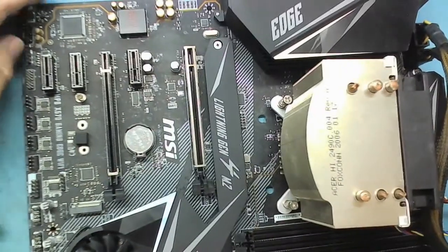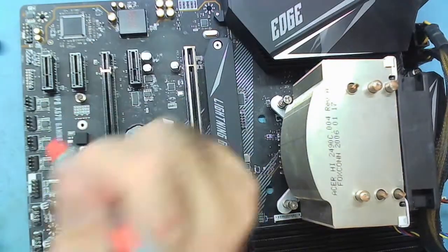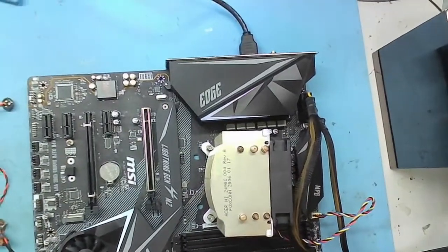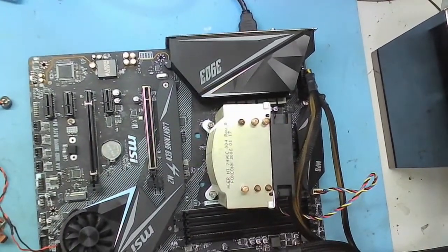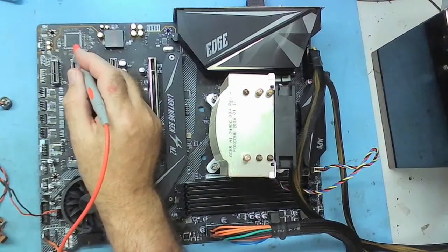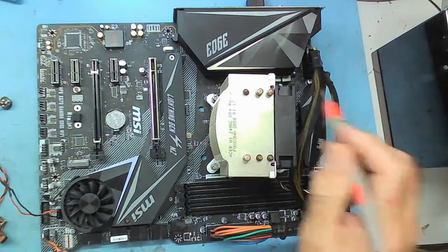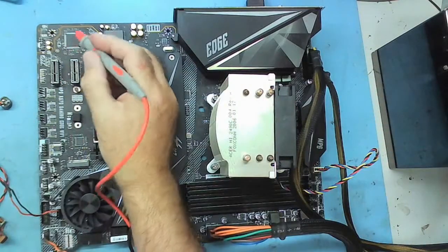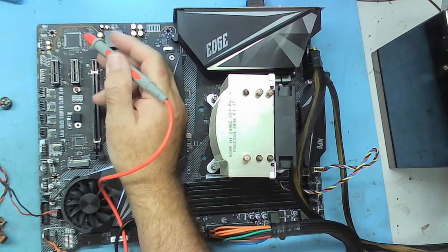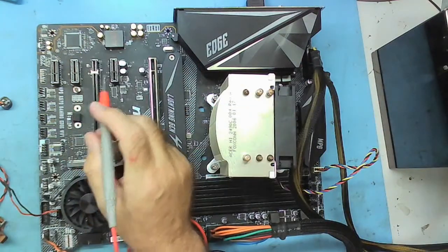Well, this is going to vary a bit from one chipset to another. But the chips that are involved in starting a board up from scratch, normally the Super I/O, which normally controls all the VRMs or tells them to switch on and tells the board to power up, yeah. I'd have to check this chipset, but I'm pretty certain that's what will do that. That will tell it to power everything up.